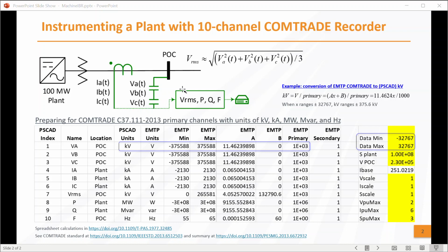In either of those tools, you can measure RMS values independently on each phase. You could also try to measure the positive sequence voltage. Those are going to be different. But what we do see sometimes is this estimate of the RMS voltage, and it can be calculated instantaneously, as a function of time, from the instantaneous values of the 3 phase voltages.